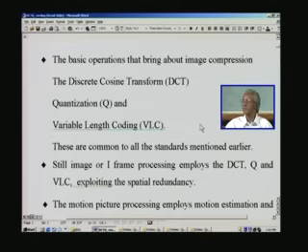The architecture also plays a great role in that. The purpose of applying variable length coding is to bring about compression, and the compression effected in this stage is even more when compared to the quantization stage, since it succeeds in transforming most of the coefficients to 0, which need not be broadcast and need not even be coded.